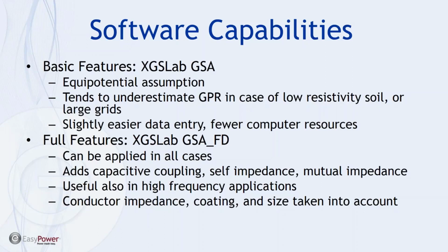Stepping into the next level, what we've termed the start of fully featured software, is what XGS Lab terms their GSA FD product. FD stands for frequency domain. This is the beginning of the fully featured sort of thing. It's similar to the CDEGS MALZ or multi-ground Z module. The main change between this and the last one is that the equipotential assumption is now gone.